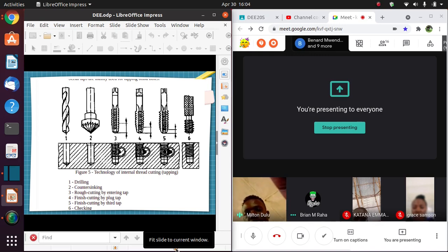This is to reduce the stresses that the drilling machine will experience. If you go to drill a big hole and pick a big drill bit and start drilling, that drill bit might break or your drilling machine might break. So you drill slowly as you increase the diameter of your drill bit.